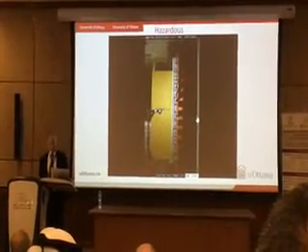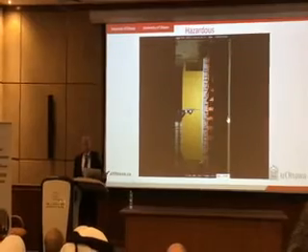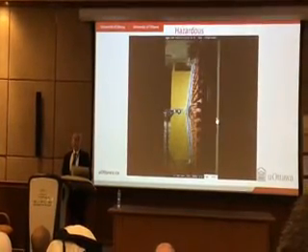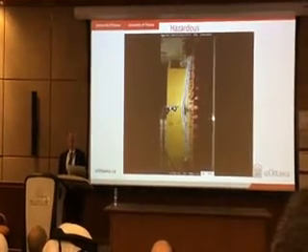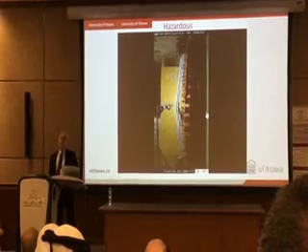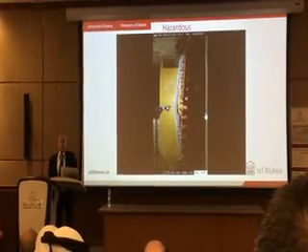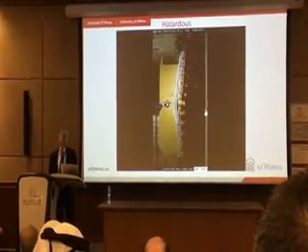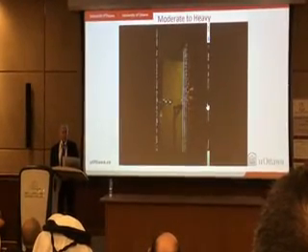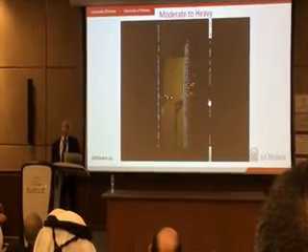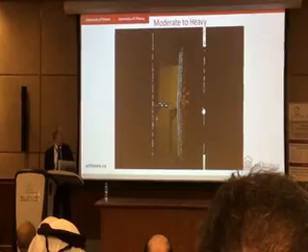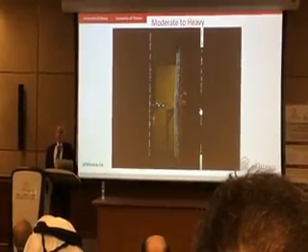Now, hazardous failure is not as bad, but it is still bad enough that you may not be able to use the building, because as you can see, there's a permanent deformation. Concrete spalled off and steel has yielded. This is quite high, and it is not acceptable if it's in main elements. Now, moderate to heavy is acceptable depending on how much repair you want to use. And this has a little bit of permanent deformation.